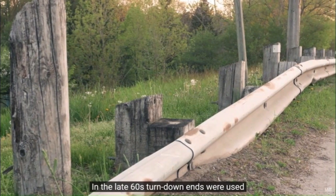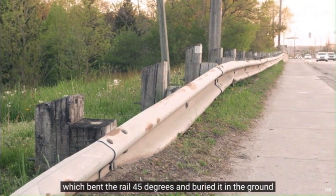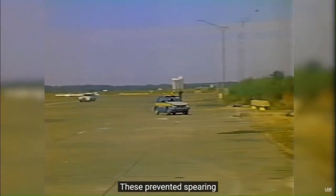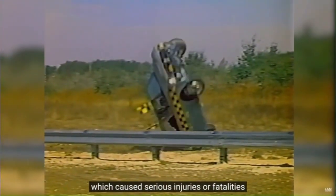In the late 60s, turn-down ends were used, which bent the rail 45 degrees and buried it in the ground. These prevented spearing, but vehicles could easily vault or roll over, which caused serious injuries or fatalities.